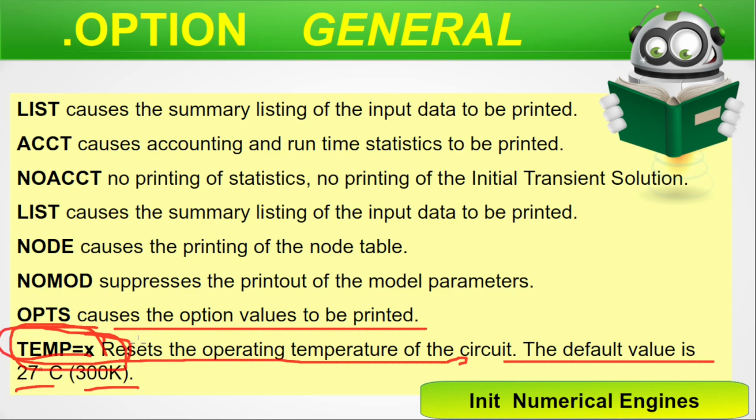So the process file comes from SS, TT, etc. I have shown you the model files, how they are included, in the last episode. The voltage will be given by you as SPICE voltage commands and options, and the temperature is controlled by this. So this is very important with respect to VLSI, because PVT, that is process, voltage and temperature, is important in VLSI, and we have an entire episode on these process corners. These are called process corners or PVT corners or PTV corners. There are many names. Why are they important? Please watch the video. We have the link in the description.